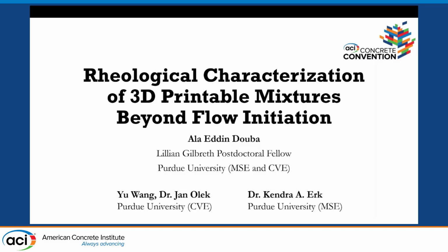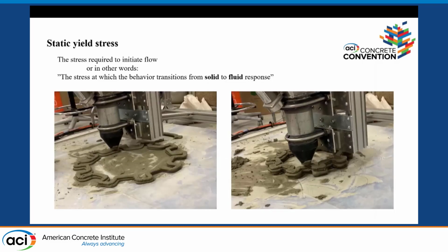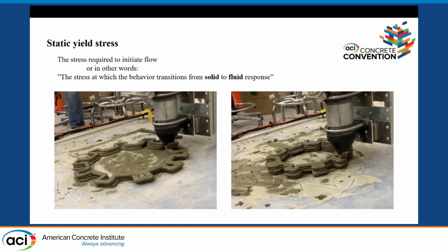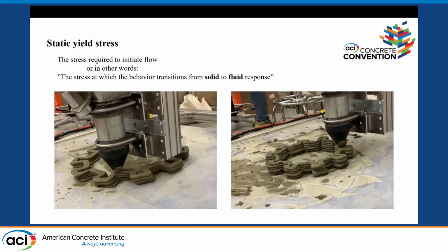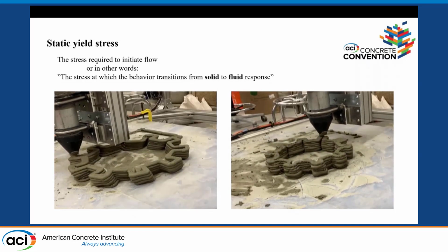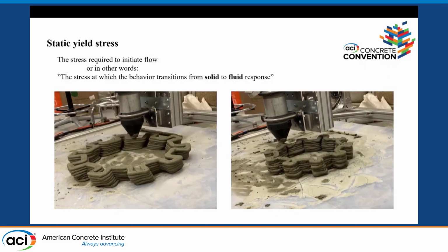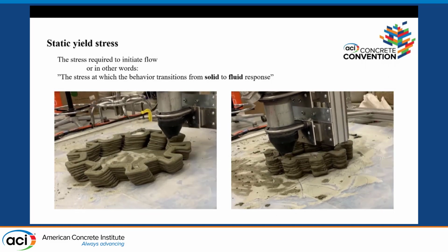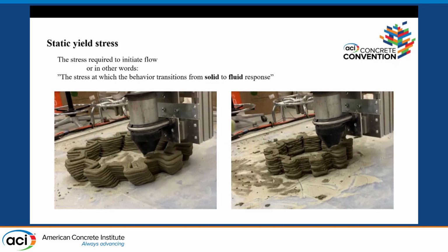Hi everyone again. So I'm going to talk about rheological characterizations of 3D printable mixtures beyond flow initiation. I picked the word flow initiation very carefully here. Probably everyone in this room would agree with the definition we typically use for the static yield stress, which is the stress required to initiate flow.